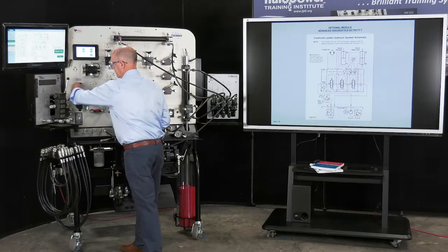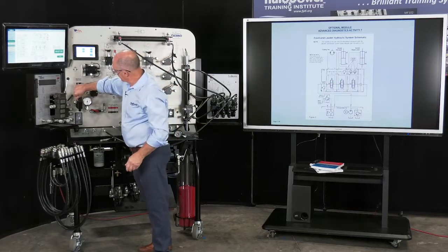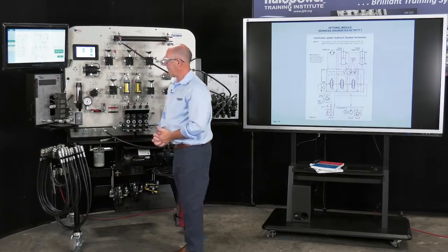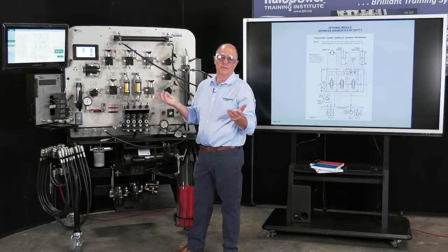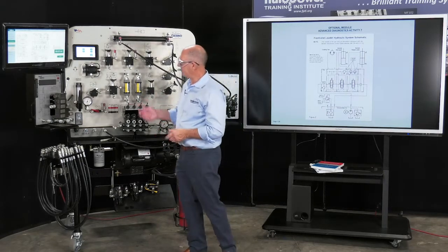So let's pump in. I'm already doing what is called a microleak test. I'm now going to pump up to any value, because you don't care about pressure here. Pressure is not an issue, it's about leakage. And you can see it's holding.